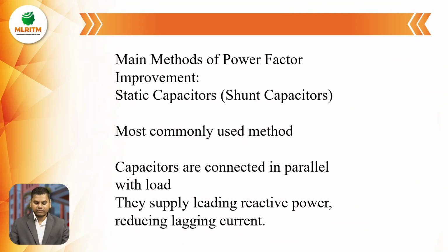So the main methods of power factor improvement here, first, static capacitors. Static capacitors are also called shunt capacitors, the most commonly used method.